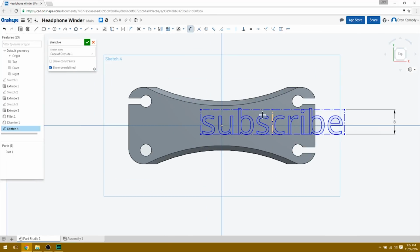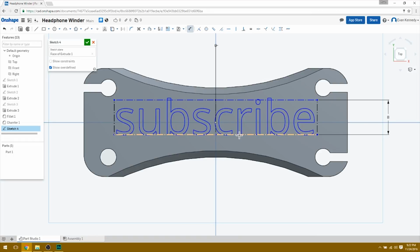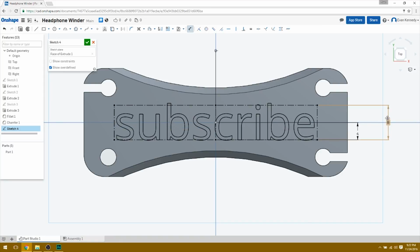Now, in order to get this centered, I can change the distance from this line here in the center of my word, and this, which is the top view, I believe, of my right plane, and I can change that to 0. And to get it centered this way, there's a few different ways that you could do it. I'm just going to do it by eye. So, well, actually what I can do is I've set that to 8, so I can change the distance from the bottom edge of this to my origin, which is there, and I can change that to half of 8. So again, if I don't know what half of 8 is, I can type in 8 divided by 2, and that changes it to 4.